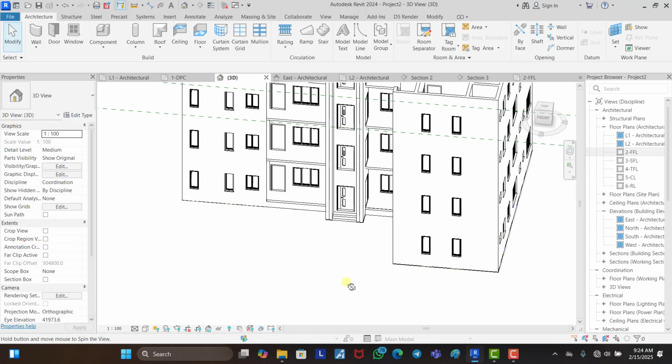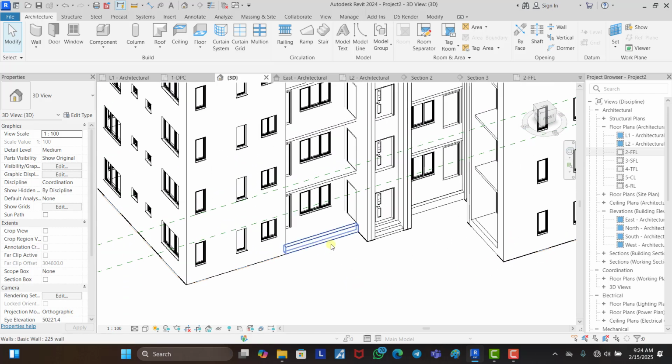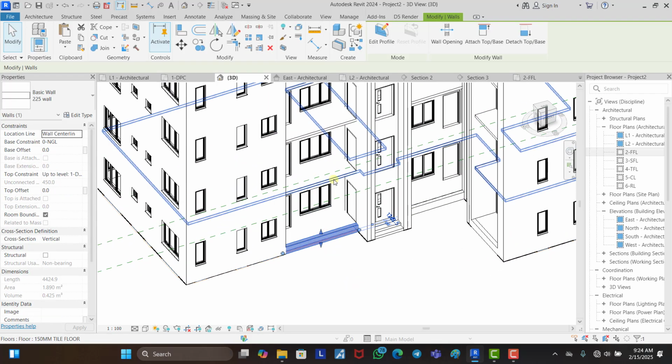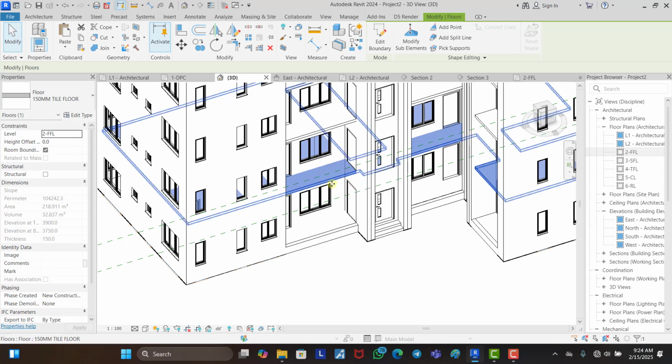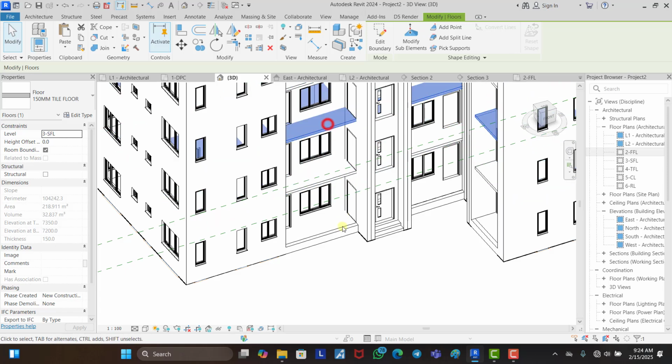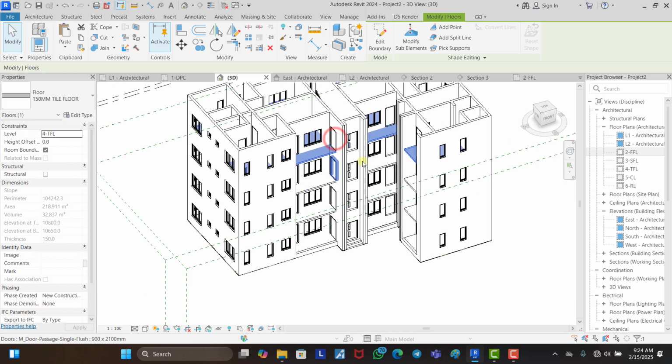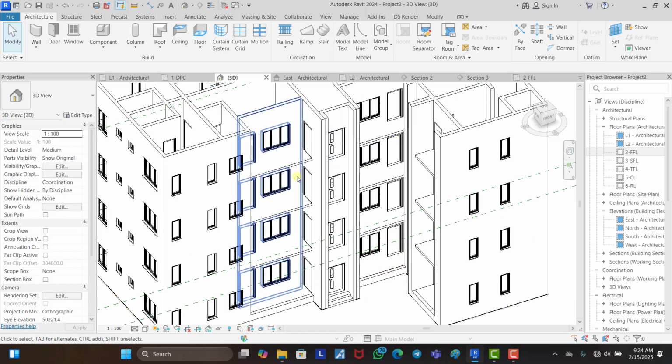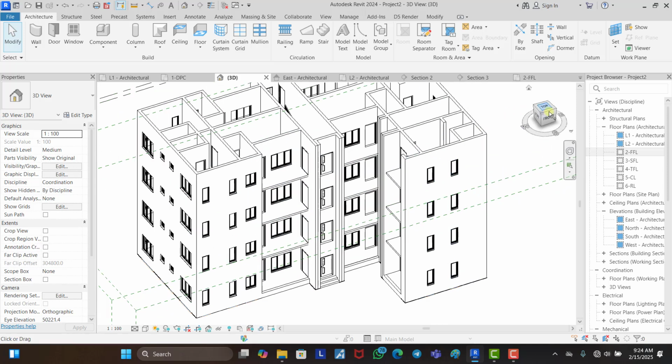Then the next thing to do now, as you've created this one here, now you can't just have your floor hanging, the floors above, you can't just have them hanging on nothing. So you need to create a beam at that point, and probably an upstand too at that point. Okay, so I'm going to explain what I mean by the beam and the upstand. So we're going to be using walls to create them now. Okay, so let's create them.